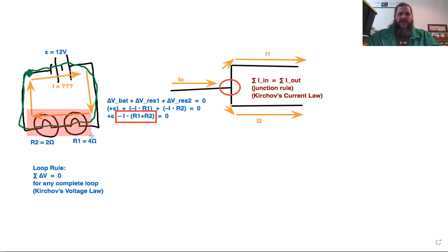And how would you describe, yeah, these are in series, right? We put these resistors together in series, which forces them to have the same current. Same current means we can factor that out. So all that's left is the resistances added together. Two or more, could be any number of resistors in series, act like one big resistor with the resistances just added up. And the reason that works in the first place is because they have to have the same current, and so you can factor that out.